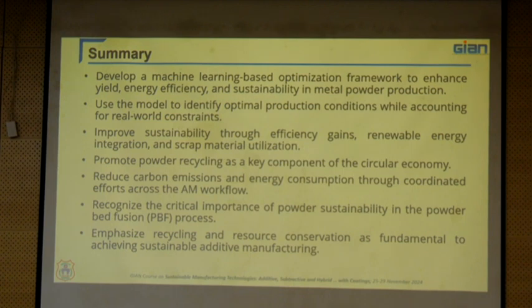And also recognize the critical importance of powder sustainability in the powder bed fusion process, because in powder bed fusion almost 60% powder wastage will be there. The entire build area is not a complete solid block; depending on the structures, and the support structures we have to provide, almost 60% wastage will be there. Then we need to think about how critically powder sustainability can be addressed in PBF, emphasizing recycling and resource conservation as fundamental to achieving sustainability in additive manufacturing. These are all the things we need to understand to apply sustainability in our additive manufacturing process.